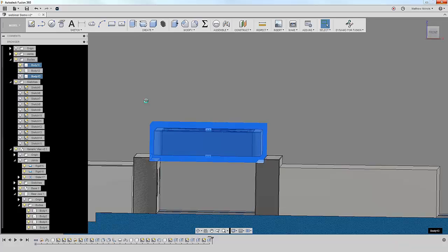In the case of making the soft jaws, does it require going back to any of those parameters of the model? The way that I have them constructed, which could actually be done a whole lot better, if you modify this, I would basically have to delete the soft jaws and the stock and just redo it, because I don't have them putting any kind of parameters into my model. It's just throwing geometry in there and creating the solids from what I defined.